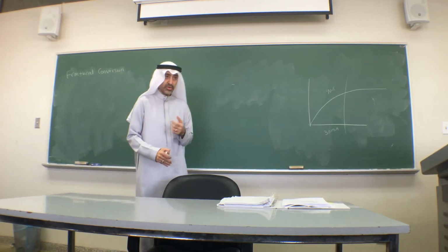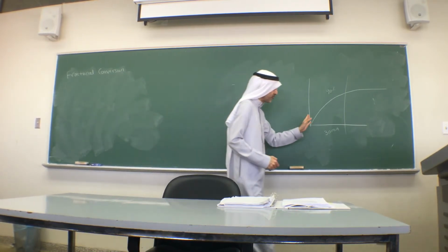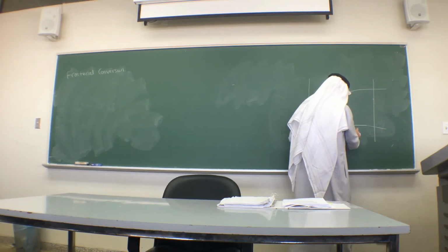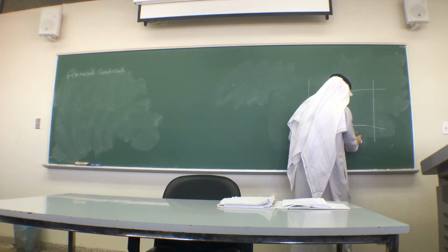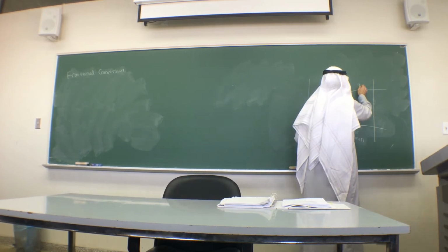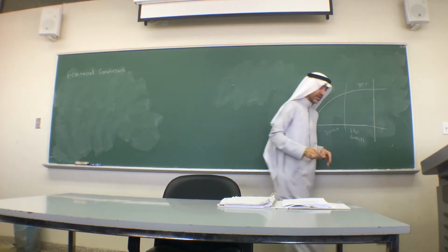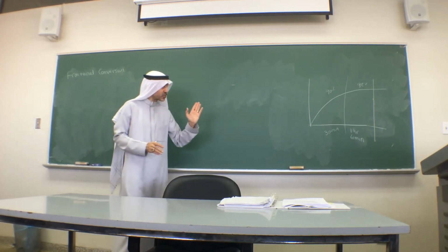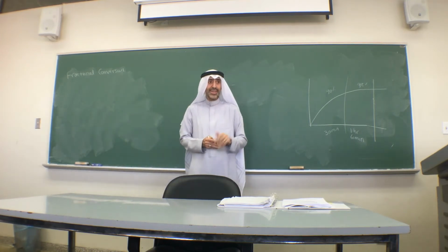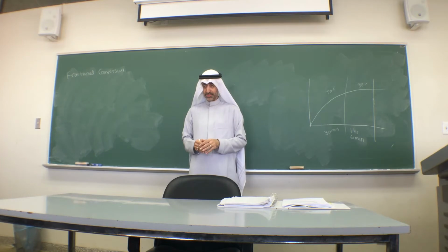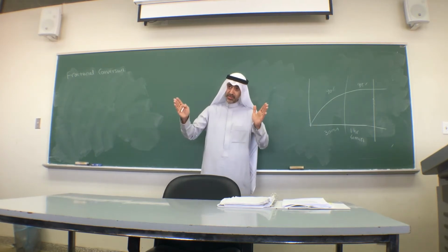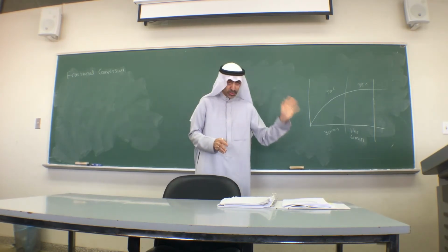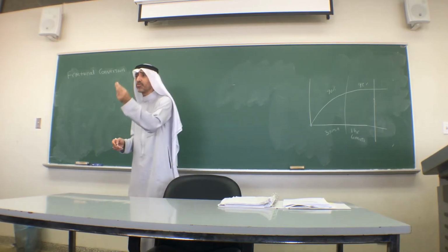No, I need more. There is no problem. So if you continue, you will find yourself maybe after 1 hour, which is 60 minutes, you get 98%, for example. Now think about it. If in the first 30 minutes you achieve 90%, is it worth it to wait another 30 minutes to get an extra 8%? Notice here I'm talking about conversion. I'm not talking about purity. I'm not talking about anything else.